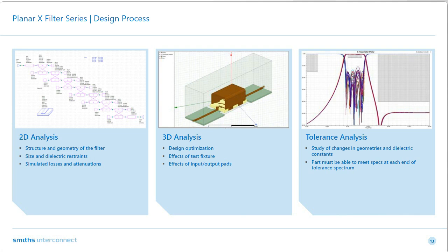With printed filters, just like every other filter technology, the designs must follow a rigorous design process to ensure efficiency and compliance. After receiving specifications, a feasibility analysis is performed. It is during this stage where we determine what type of topology or technology a filter would need to be. If a specification comes in with kilowatts worth of power needed or ultimate rejections below 100 dB, we know printed filters will not be the solution.